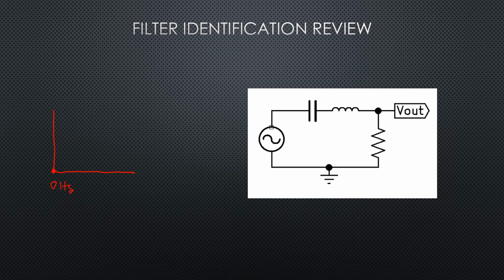And let's imagine we're approaching infinity, like a really high frequency. The capacitor reactance is going to be very, very close to zero, but the inductive reactance is going to be approaching infinity. So again, we're not going to have any circuit current, so the output is going to be 0 volts.